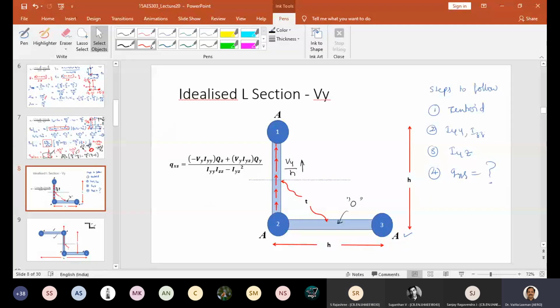Even the C-section you see that. You can see that here is going to have V by H, whereas this is Vy by 2H or 3H, depends on the areas. If I'm having 2, this is A and this is 3A, 2A is going to be Vy by 3H. So this value reduces as the stringer is increasing. That's it.